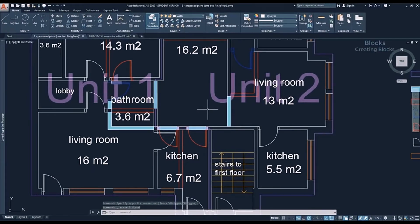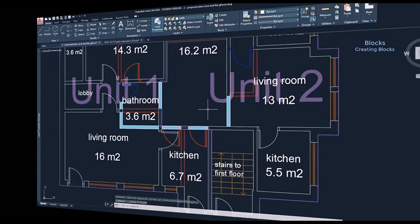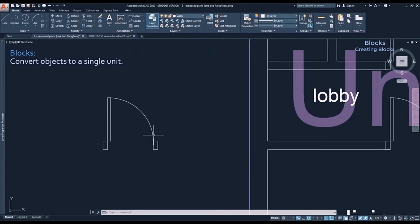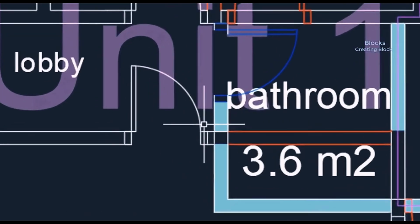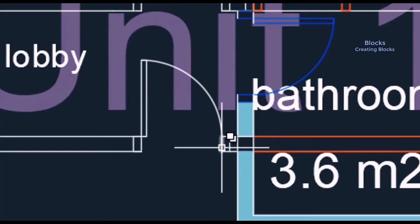Sometimes we draw something that it's easier if it would be a single unit. For example, a door. If we want to copy it, I have to select all the objects that compound the door. If we convert all these objects to a block, they act like a single object.